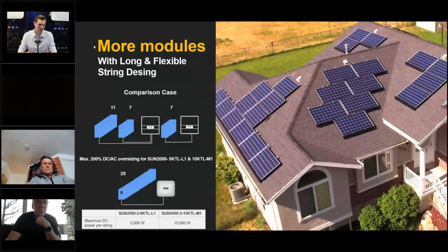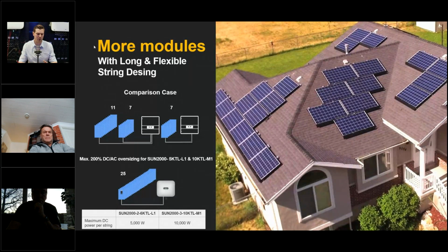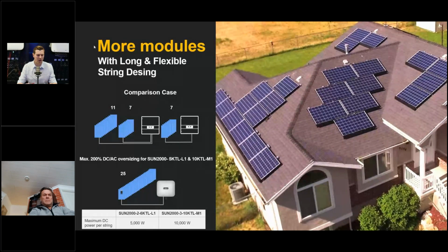At some point, the inverter could withstand much more power, but this voltage limit is a border we mustn't cross. If we use full optimization, the system will decrease the output voltage of the string and increase the output current, so at the same time we will have the power transfer. In this case, we could connect more and more PV modules in one string and make our system work efficiently. In the residential market, this system can be used mostly for having more flexibility when it comes to the design.